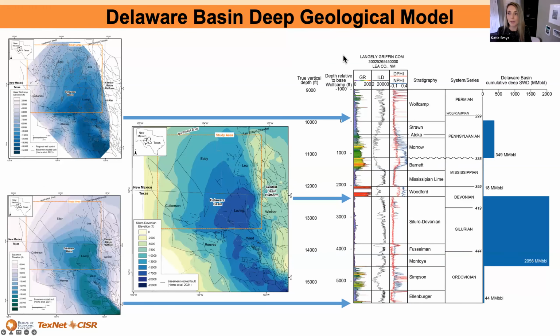What we've done then is build a pretty detailed geologic model. We have the structural interpretation from the team, and now we look at the deep injection strata themselves. So what are their structure, thicknesses, and reservoir properties? This will eventually populate a 3D geocellular model and a pore pressure model that allows us to model and map pore pressure and stress changes that we can then integrate with our fault interpretation.